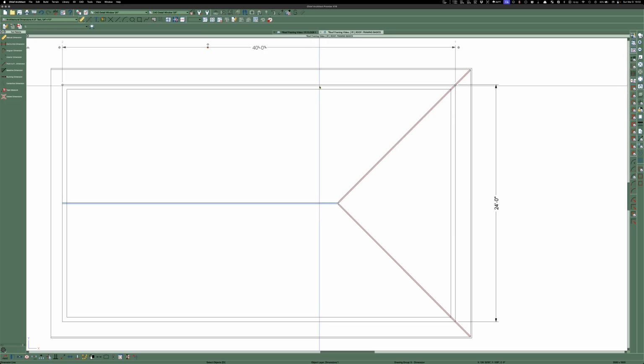They would make the seat cut whatever it took to come over to the inside of the wall, so that you'd have the maximum amount of the rafter sitting on the plate. Well, you can't do that with a 2x8 or a 2x6 if your wall is 2x6, because it's just too wide. You'll cut most of the rafter off. You won't have enough meat to hold the tail out there.